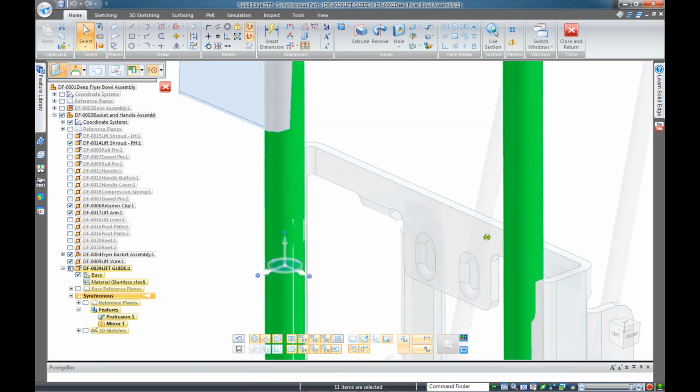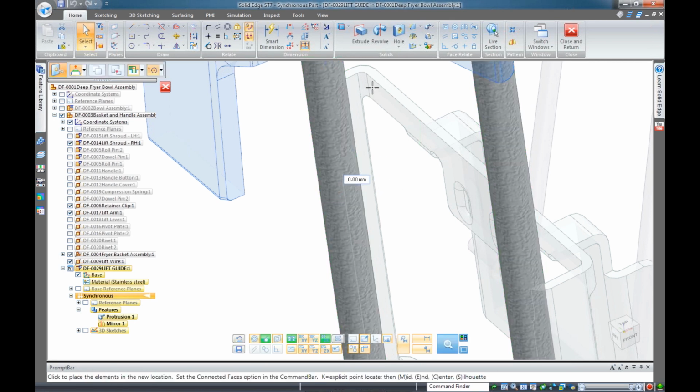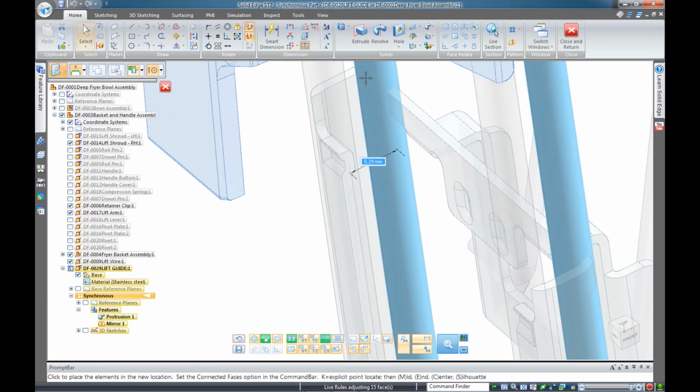Come over here. Now, I want the back side of this flush with the inside part of the sheet metal bracket. I can simply do that by using my steering wheel, offset it half the distance of my diameter, and use my key points.